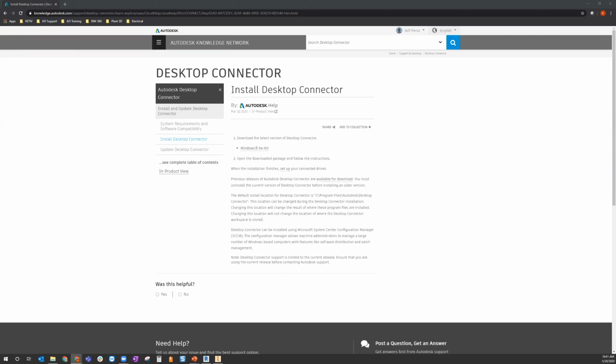So I would use some of the simplification tools within Inventor to simplify that model design, and then go to the BIM content export that I just mentioned a little bit ago to publish my RFA file from Inventor. And with that RFA file, it should be a lot smaller file size, so that when it's being brought into your Revit model, it shouldn't really hinder the performance at all, just because it is a native RFA file. It's almost like a part file within Inventor.